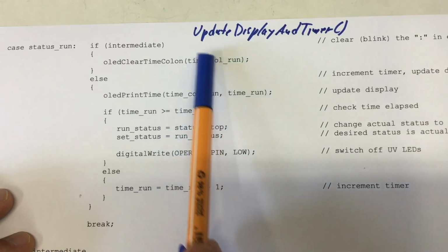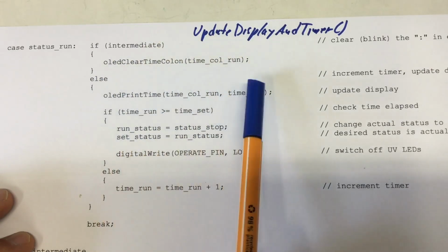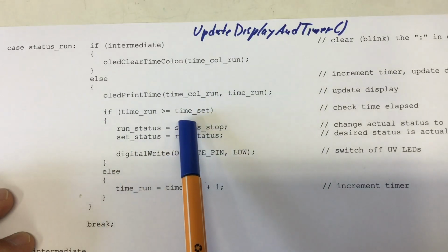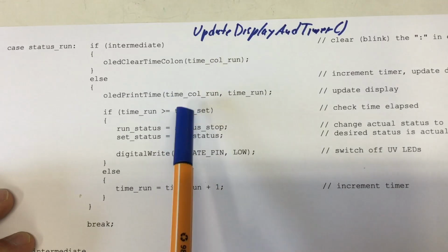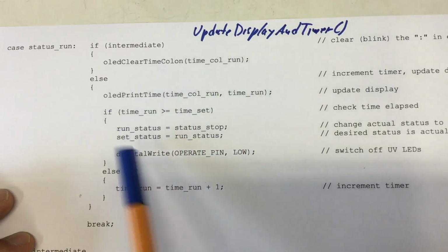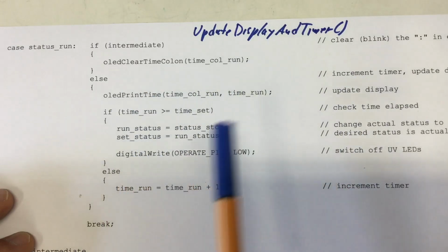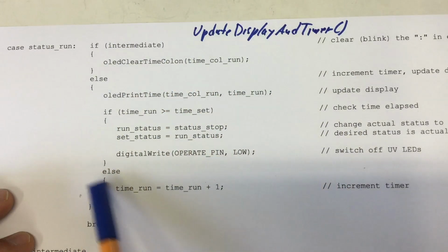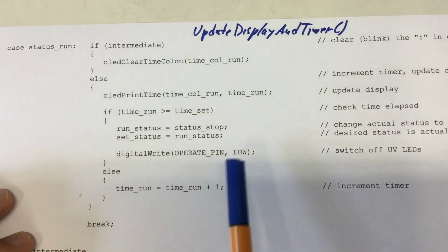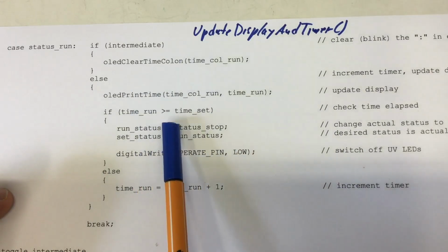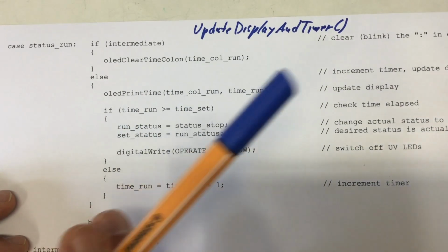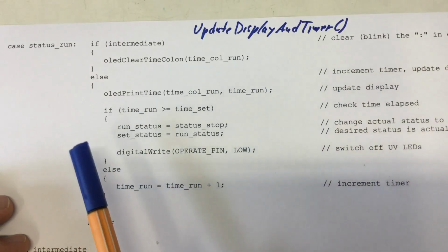So while the keypad is polling and doing some timing stuff for debouncing and so on, this interrupt routine might kick in and then all the timing is off. So I just rewrote it on the top level, all for polling. So basically that's all that happened, and let's see what happened to my exposure unit meanwhile.